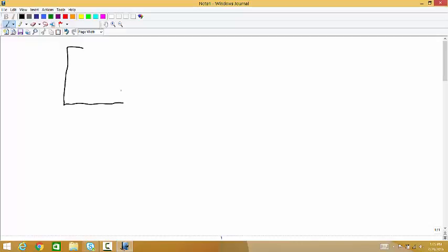If I exaggerate the wall thickness in this drawing, we have a thicker wall there, thinner everywhere else, and you're calculating the stress at two places. One's here and one's here.